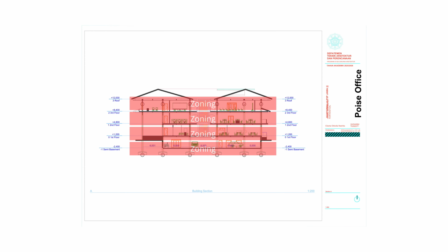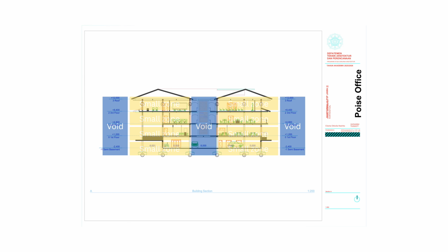Instead of dividing everything into many separate zones, I organized the zoning more clearly. The courtyard stayed in the middle. Its purpose was to break one large mass into smaller parts while keeping the circulation simple. Now, the courtyard could finally serve its real purpose. It brought daylight, it improved natural ventilation, and it connected many spaces at once. My passive design concept finally started to work.